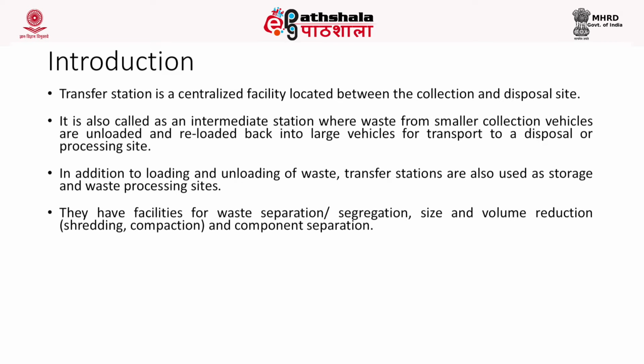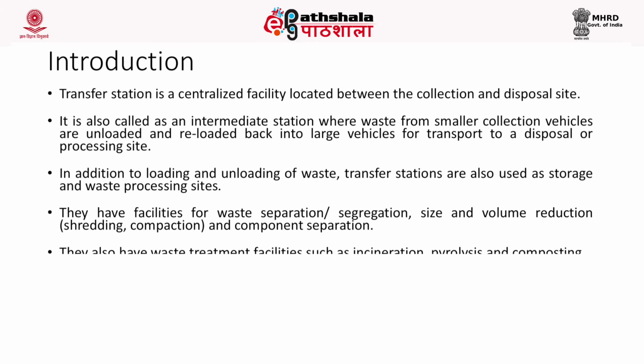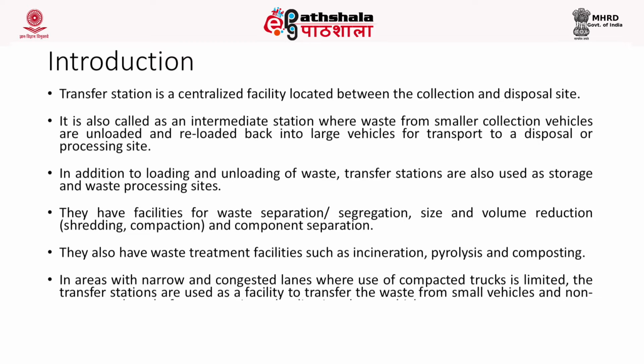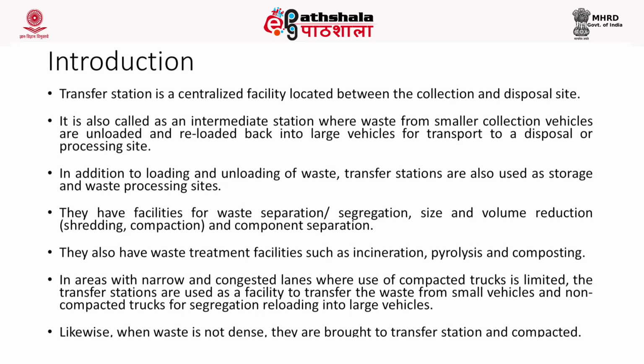In addition to loading and unloading, transfer stations are also used as temporary storage and waste processing sites. They have facilities for waste segregation, separation, size and volume reduction, for example, shredders, compactors and so on, and even component separation is done in a transfer station.